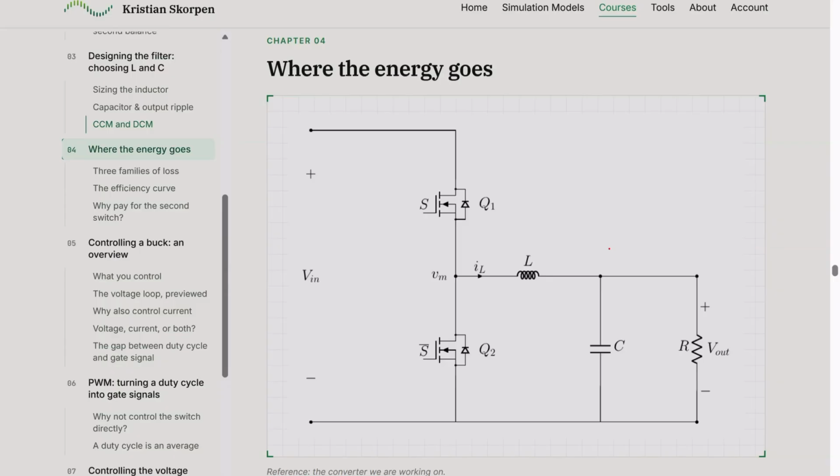And then we have the last kind of loss, and that is magnetics losses, which is only in the inductor here. It comes basically from a changing flux. The ripple of the current is linear with the flux density inside the inductor. So this could, for example, be the flux density. The peak-to-peak flux density has a positive relationship with the power loss. So basically, the larger the peak-to-peak flux density we have, the larger losses we have.